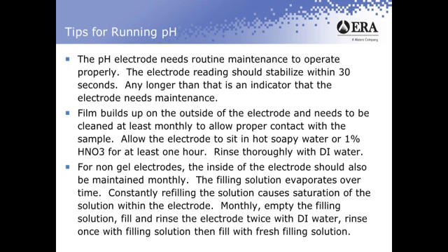Periodically you might also see some crystals sitting down in the bottom of your electrode. Those crystals are the supersaturation of the silver chloride solution inside the electrode, and that's a pretty good sign that it's time to clean that electrode. So what I'd recommend, at least monthly if not more often, is to empty that filling solution out of the electrode. I'd recommend doing that in a fashion similar to shaking a thermometer that you hold in your hand. So you want to slowly shake like you're shaking a thermometer and allow that solution to come out of the hole.